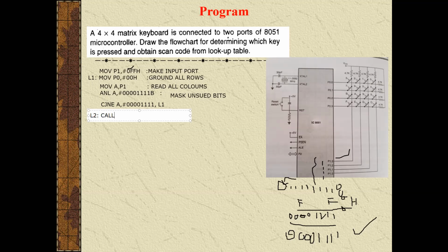This is the software debouncing, where we are using a delay. So I am calling a delay of 20 milliseconds. We are waiting for 20 milliseconds.